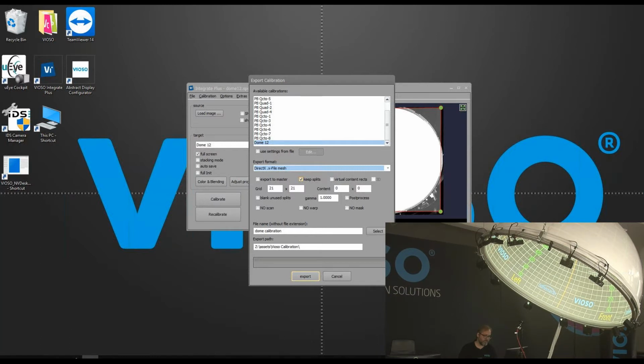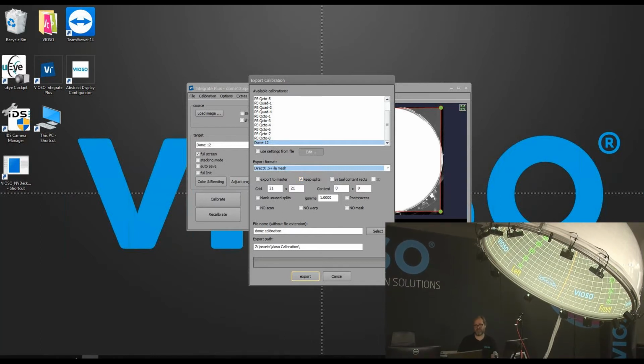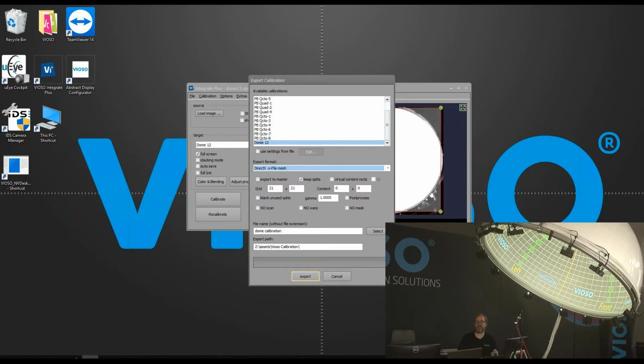It is important to have the checkbox Keep Splits checked because that will provide a single file per projector. You can always read that in our tutorial, so you don't need to take notes or remember at which time in the video it's explained. So DirectX mesh file and Keep Splits. These are the settings that you as an operator need to do when working with Pandoras Box.